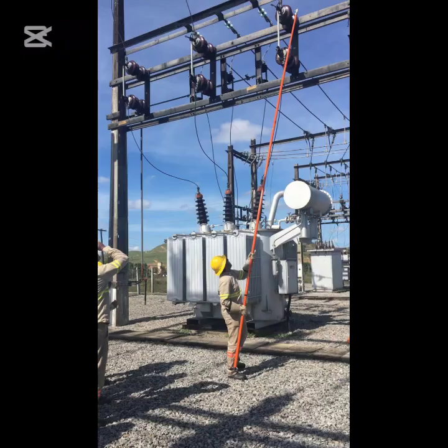As you have understood how a transformer works, it is important to know some key points about transformers. Things that don't change when a transformer is transforming: 1. Frequency of the AC voltage. The frequency remains constant, for example, 50 Hz or 60 Hz, regardless of voltage change. 2. Power conservation. In an ideal transformer, the power is conserved. Power in the primary equals power out in the secondary.